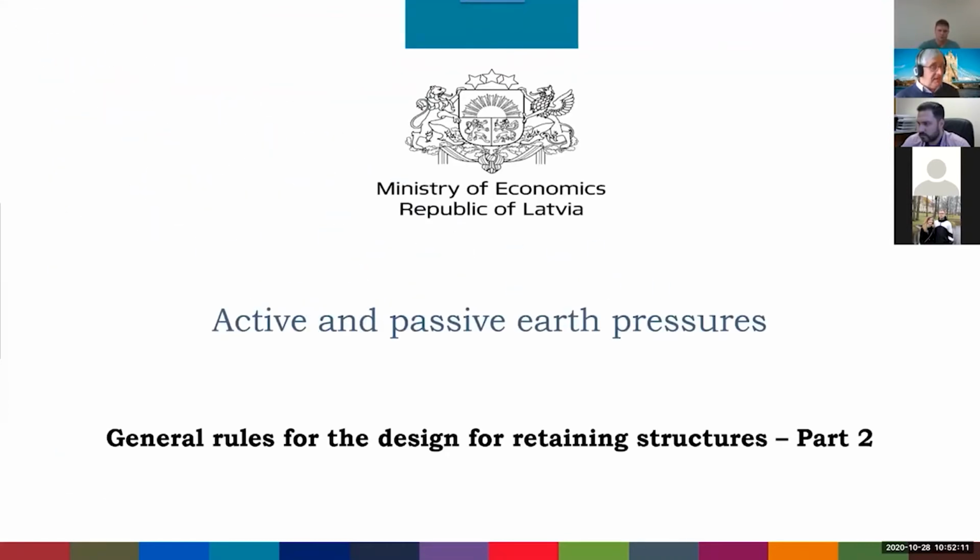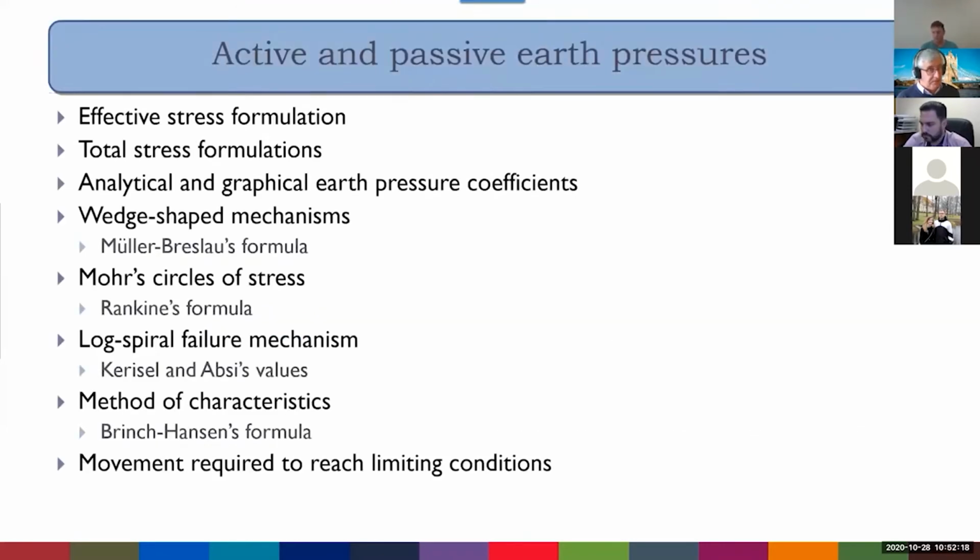So the first thing that we look at with earth pressures is whether that is the condition, whether we're at what is called a limiting state, active or passive earth pressures. And there are a number of ways of getting these values, which are the values that you will use in ultimate limit state calculation. So when you're doing your ultimate limit state calculation, you're going to be pushing the wall to failure so that you can show that it doesn't occur. And that means you will quite often approach an active or a passive limit state. And I'm going to cover all of the topics shown here.